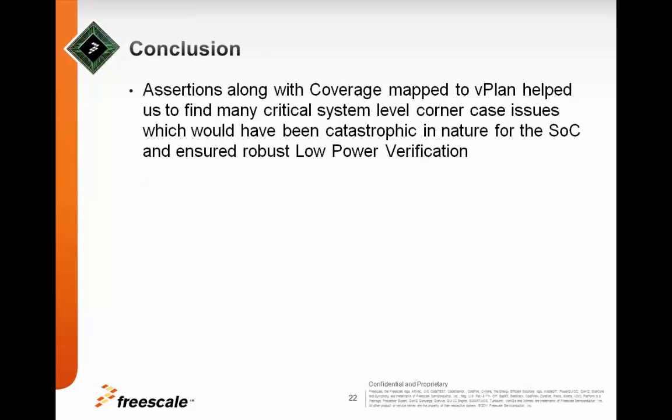Conclusion: the dynamic simulation driven approach proves to be cycle time and debug effort intensive when it comes to catching the low power integration and design issues. Assertions targeted towards the low power verification can help to provide a smart path in reducing the cycle time and to help catch the issues early in verification.